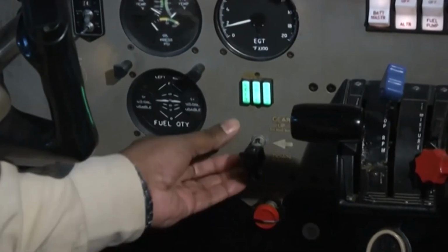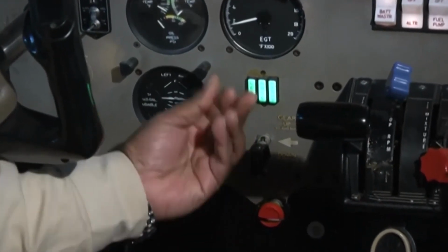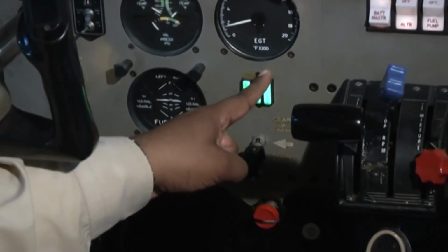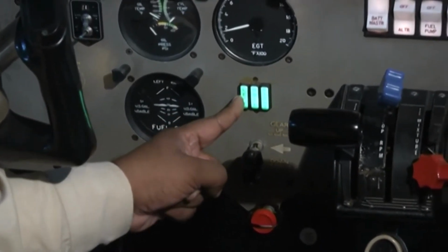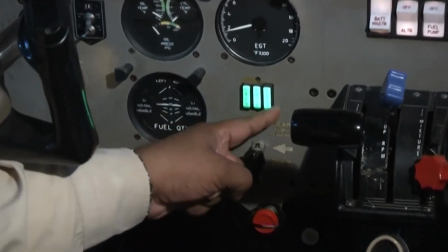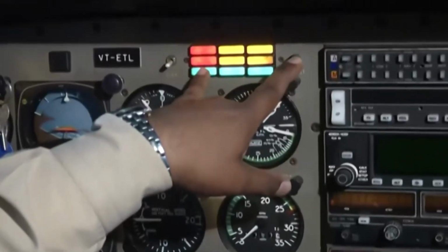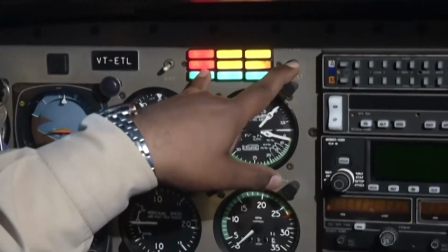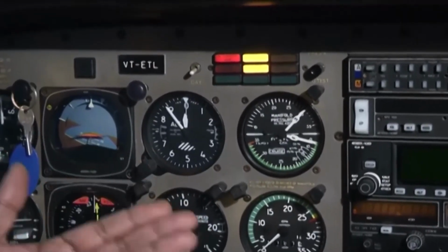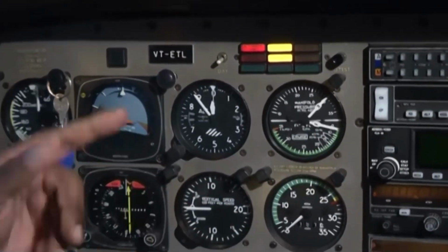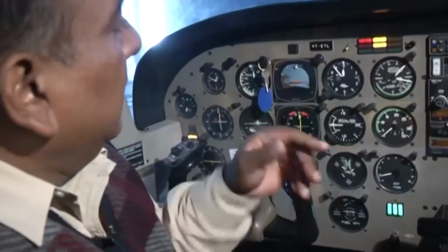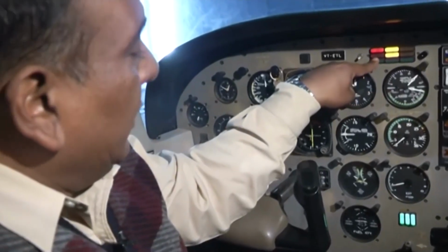After taking off, once the pilot selects this lever up, then these 3 lights will go out. That indicates now your landing gear is not in the down and locked position. Once these lights go out, you can see here a red light, gear warning light. This light will glow. This indicates that now your landing gear is neither down and locked nor up and locked and is in the transit mode. Once the landing gear is up and locked, this red light will also go out.